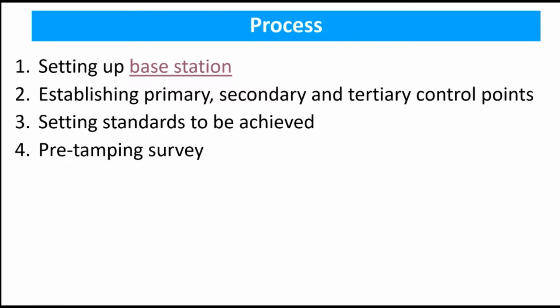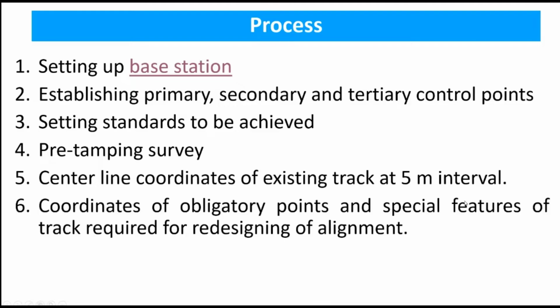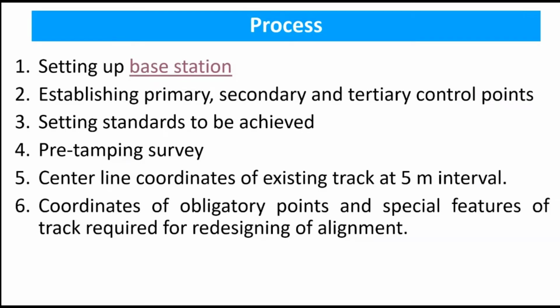Then we do the pre-tamping survey. We will discuss in detail what the pre-tamping survey is. In the pre-tamping survey we need coordinates at 5 meter interval. Then we need coordinates of the obligatory points and special features for redesigning the alignment.